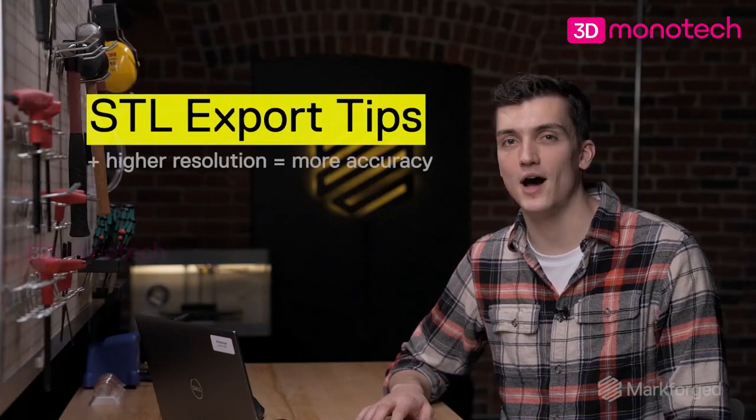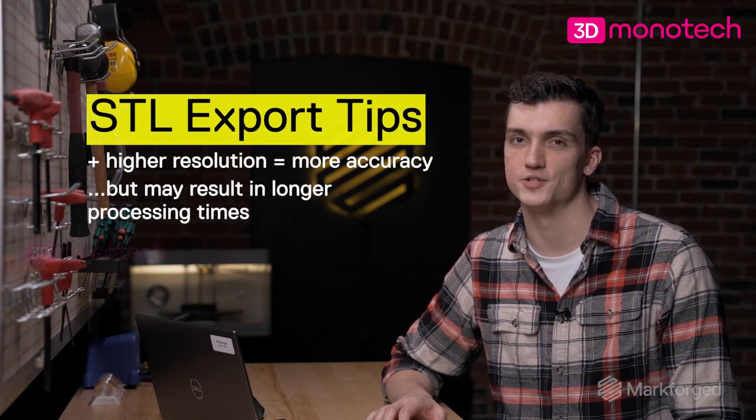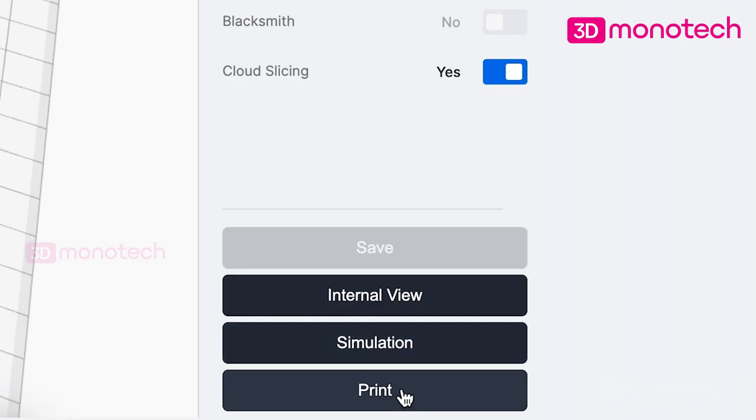We now know that a higher resolution STL mesh will produce a smoother, more accurate model, but don't feel like you need to crank up the resolution all the way. After a certain point, the resolution will just exceed the precision of your printer and result in longer processing times for your slicer. Lastly, if you're not a Fusion user, our blog post features recommendations that translate these settings to SolidWorks and other CAD programs, so be sure to check that out. And just like that, you have a small, high-resolution STL file to print amazing-looking parts.